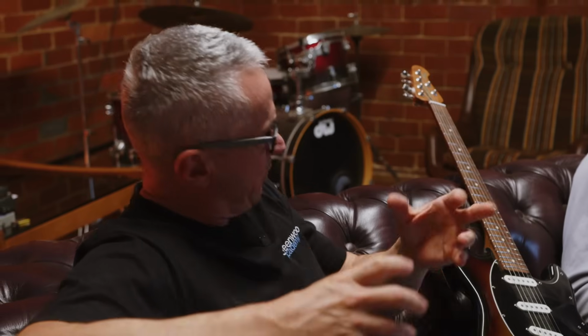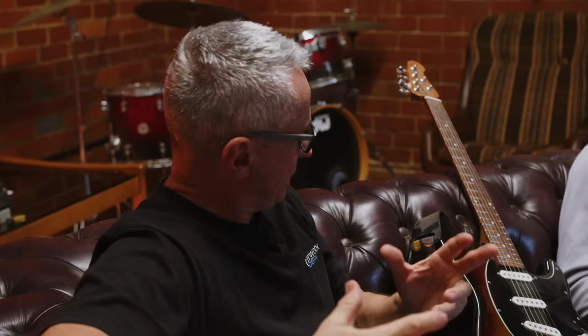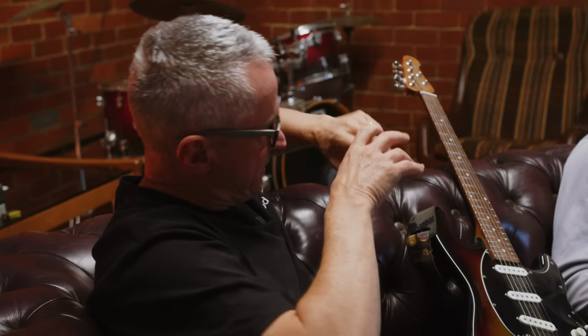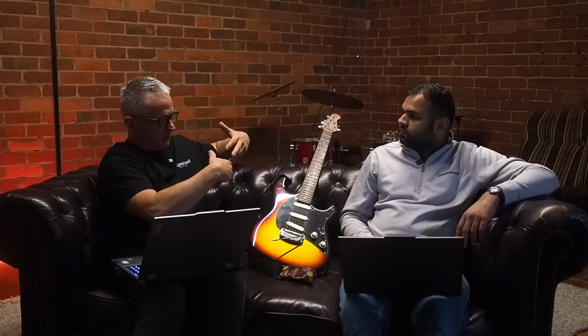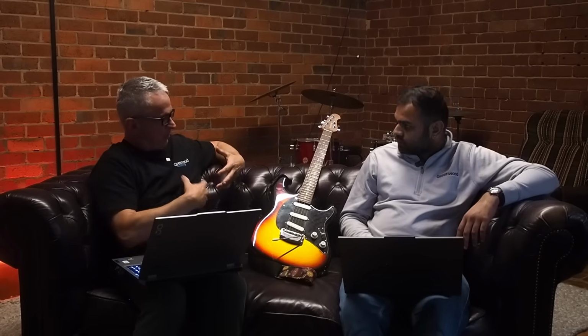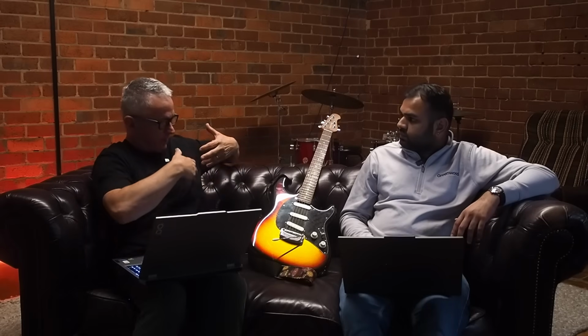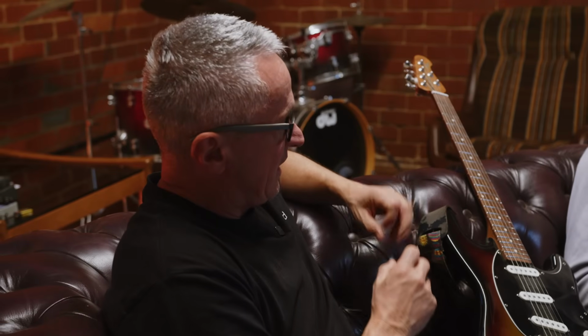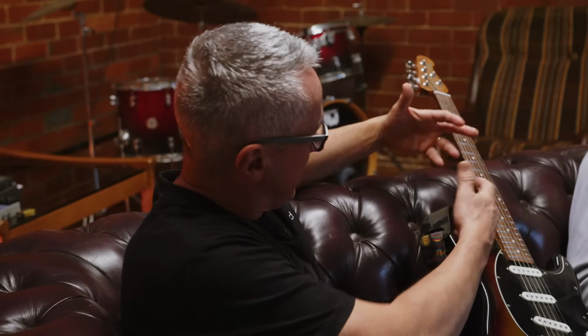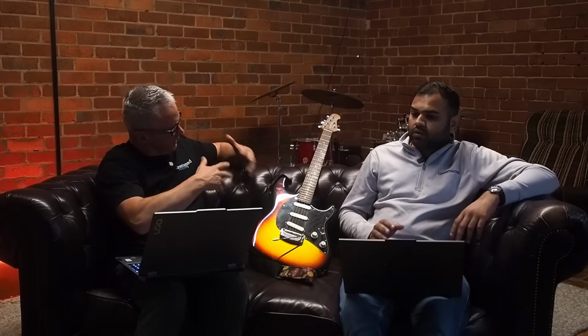And this is because we're coming along to an existing electrical infrastructure and we're saying, hey, we want to put on a 500 kVA solar system, so we have to protect that existing infrastructure electrically, and also our own electrical infrastructure, our own MCCBs or moulded case circuit breakers, the whole cables, the whole bit, and at the same time we have to coordinate with the existing system as well. Yes. So it's multi-layered, isn't it?